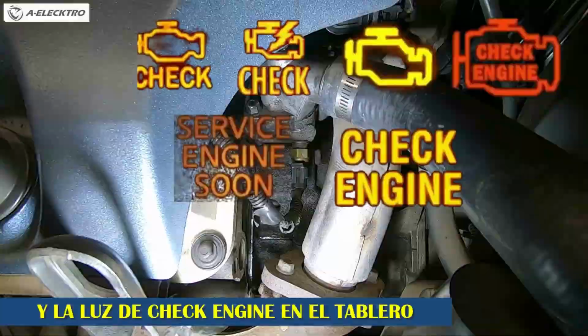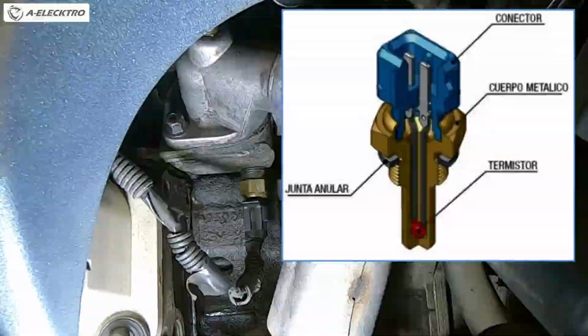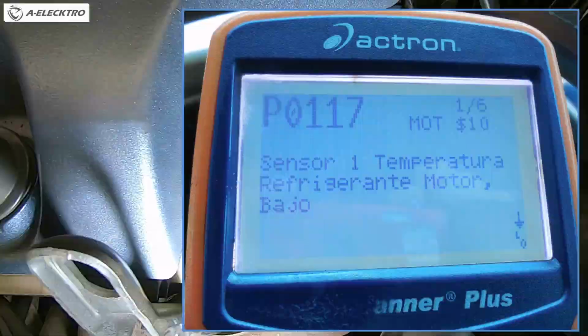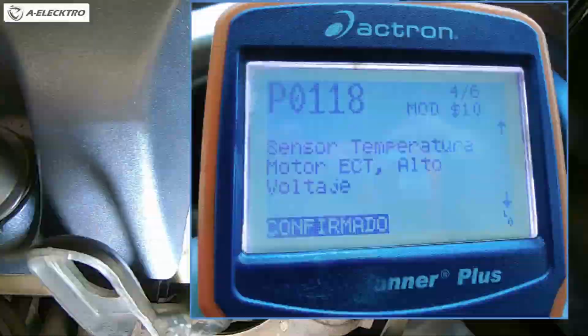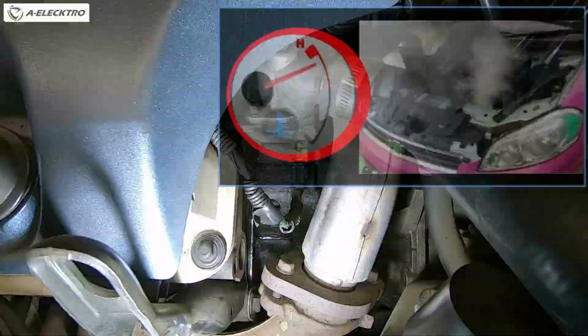In addition, fault codes related to rich mixtures and incorrect sensor voltages are likely to be generated. This problem can lead to premature engine wear and an increase in vehicle operating costs. Another problem that can arise is that the sensor freezes or only reports cold engine values.